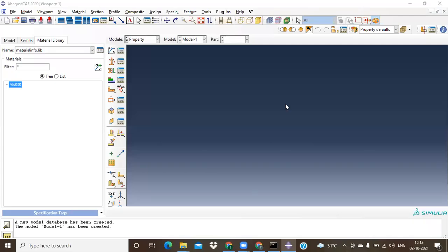So in today's session, we will try to see how to use material libraries that are already developed in past systems, or with a different version of Abaqus or a different machine. Let's say, for example, that you have saved all your material information in your lab and you want to bring it to your laptop for multiple iterations and restudy. How are we going to use this in that case? That's a challenge, right? We will see how to overcome that now.